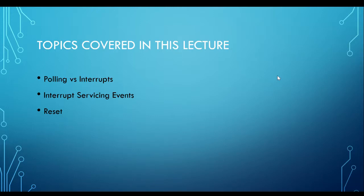It's not like a function. A function is something that you call; you already key into the main program that you're going to call it. So a function call is scheduled, whereas interrupt and polling are unscheduled. You do not know when the user will key in something on the keyboard, so your main program needs to be interrupted.